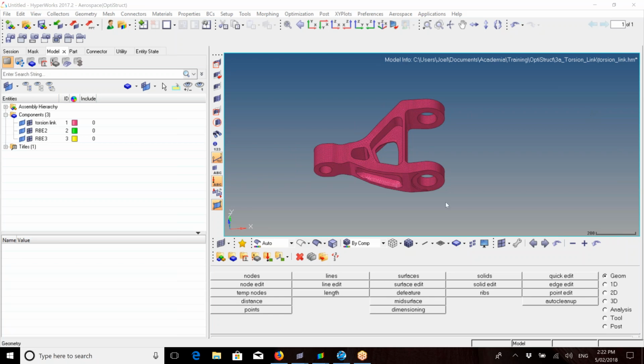So I've already got my .fem model loaded up here, but just in case everyone missed it last week, I'll just quickly recap. For this one, as we are using OptiStruct, always make sure you go to the profile here with the little person, load user profile.